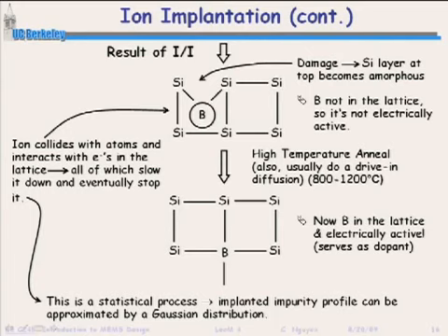And so they're going to join that lattice by occupying that defect. Okay? And so you might ask the question, well, wait a minute, that silicon doesn't have many defects. Well, it does at high temperature. When you go to high temperature, you create defects in silicon. That creates opportunities for the boron to go into those defects. Okay, that's something you learn a lot more in 243.